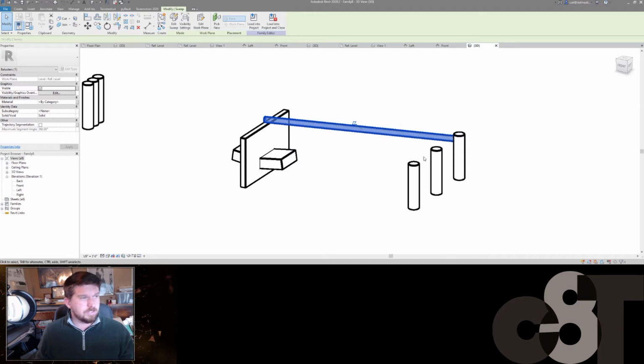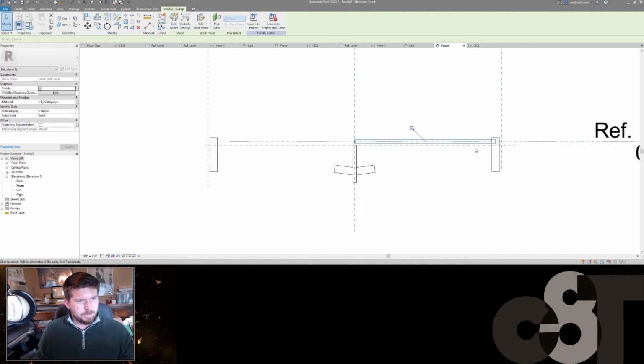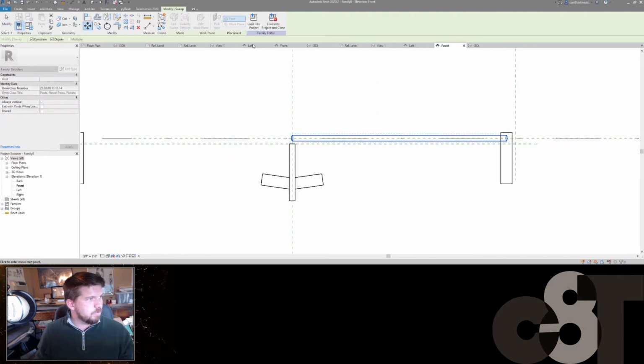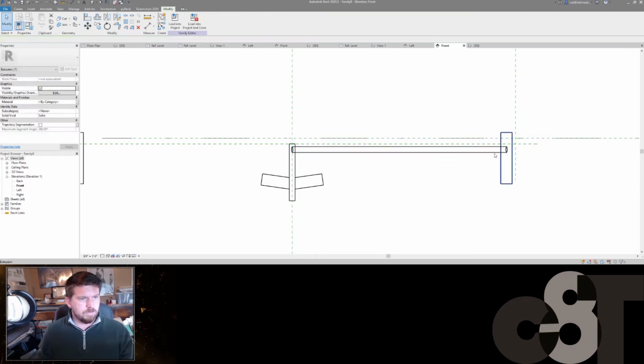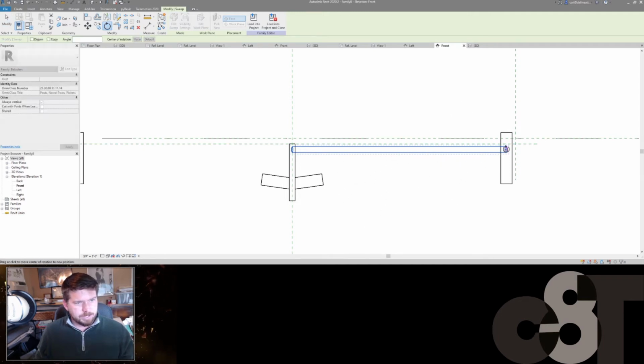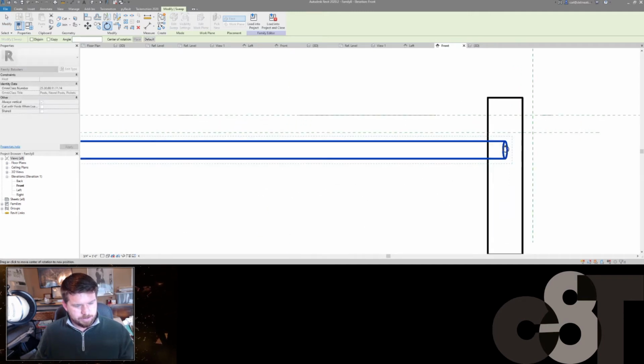Yeah, and you'll notice this looks completely wrong, and that's okay because we're going to move it around in just a little bit. So let's move this down, and when I move, all right, I'm going to hit the disjoin. I'm going to check that right there, and we're just going to move this down. I'm going to say about 1 inch. Okay, so whatever feels good to you, all right? And hopefully we're going to do it so that it doesn't disappear from us. So let's try 1 inch. And now what I'm going to do is rotate it. And I'm going to hit the space bar, and I'm going to set my rotation point. See if it'll let me. It's not going to let me get the center point of that, but that's okay.